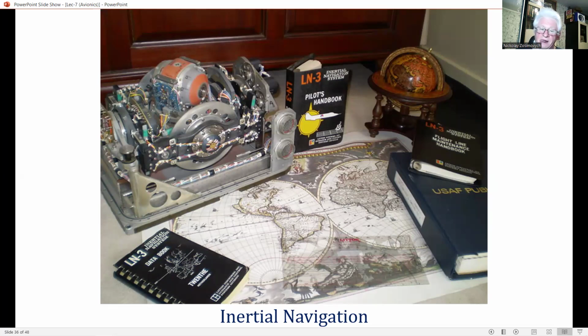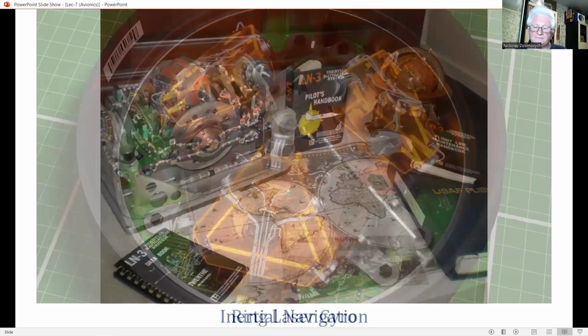High accuracy inertial navigation systems require the angular momentum gyros to be isolated from airframe angular motion because of their limited dynamic range. This is achieved by mounting them on a gimbal suspended stable platform. The reliability and cost of ownership of stable platform INS is thus inevitably limited by its complexity.